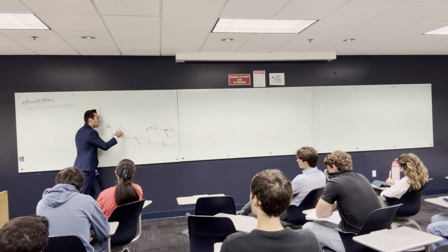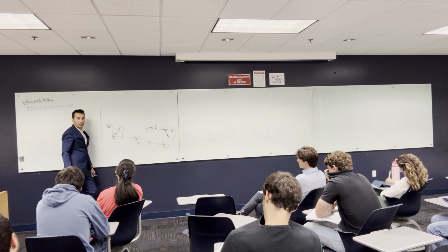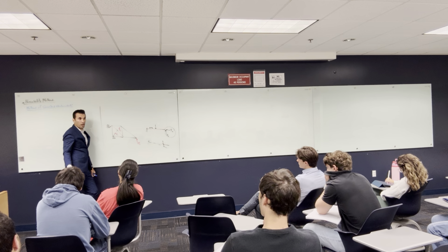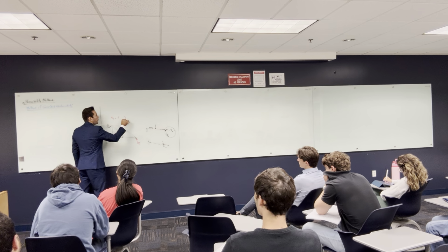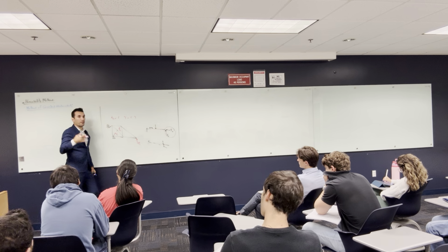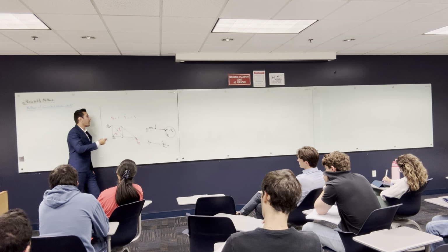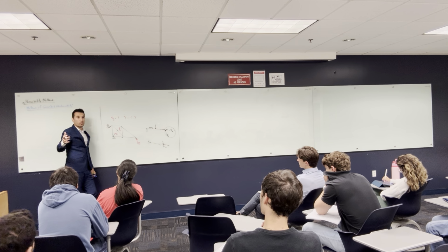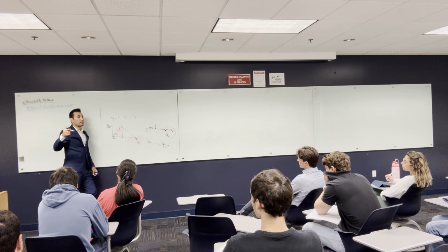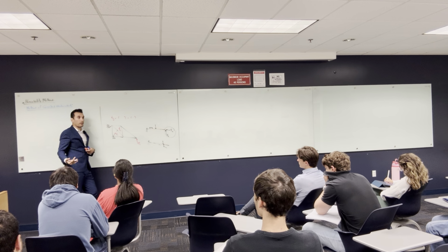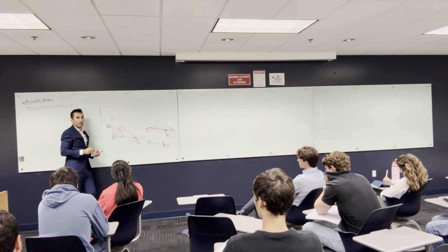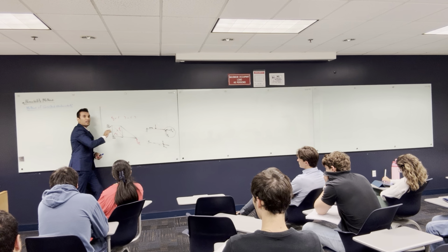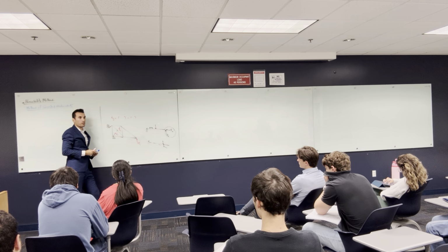So how can I know the number of redundants? Is there an equation for the number of redundants? Yes, if you guys remember, there's an IS, and you find something minus something. It depends if it's a frame or truss. Once you find the IS, try to identify if it's internal or external. So I know for sure that this is external, and there's another one internal here. When you find crosses in the truss, cross like this, definitely one of them is a redundant force.